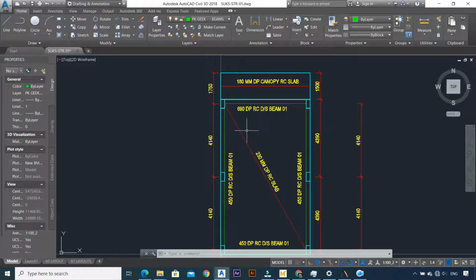And also you have to remember, if you're dealing with smaller projects, the over design factor is not that huge. What I'm trying to say is 50 millimeters of concrete on a small project will not save you a lot of money as compared to, for example, when you're doing a stadium for the World Cup, where 50 millimeters of concrete could escalate to something around 500,000 US dollars. That's why it becomes key for you to manage your numbers as the bigger the project gets, and to use less conservative methods of design.